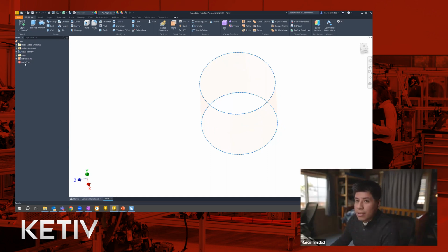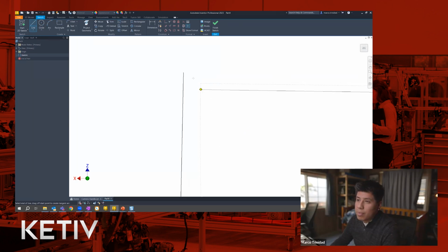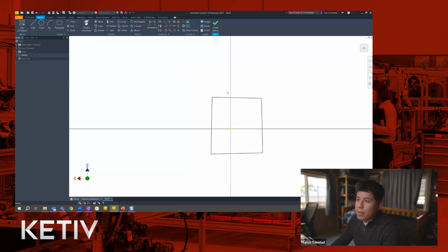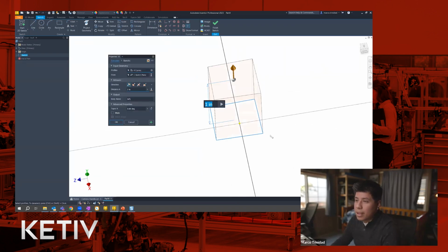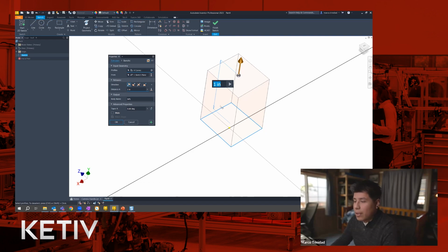And you can actually create surfaces even without a closed loop sketch. So I think one of the issues I've seen people run into is they have a sketch where they, let's say, have a design that looks, for the most part, closed loop, but let's say I set this slightly off. So from a distance, it does look like it is a closed loop, but then they run into this where it's a surface when they get to the extrude. So if you're not careful, you might have a surface come out of your sketch.